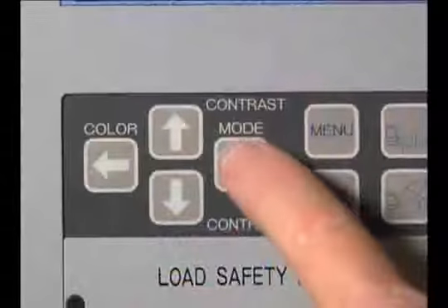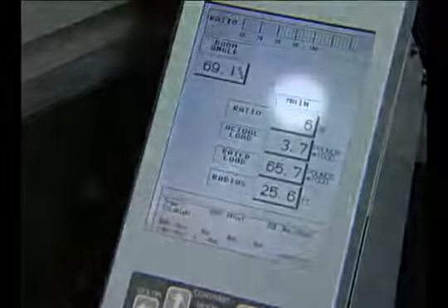The boom angle indicates the present boom angle and will instantly change as boom function is operated. The point elevation display gives the operator the current point height from the ground. The word main is an indication to the operator that the screen is set to the main hook or auxiliary hook. Press the mode button and hold it for 3 seconds to change hook status from main to auxiliary.